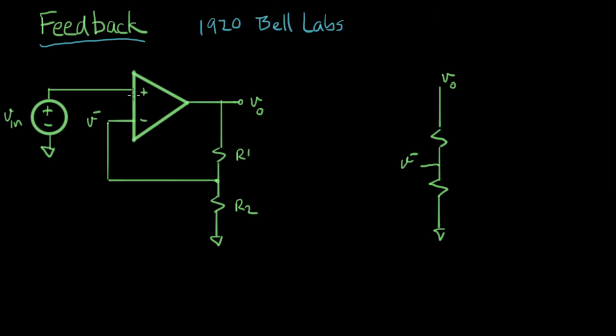Remember we talked about this on the op amp, this being the non-inverting input. So if this voltage went up, this voltage went up, and the negative sign is the inverting input. So the voltages here and here move in opposite directions. And the key to understanding what feedback is, is to pay attention to this inversion path and these non-inverting paths. We're going to start over here with just isolating the voltage divider part of our circuit. So that's copied over here.